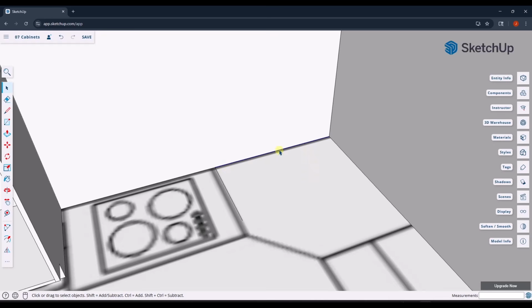So usually what I'll do is I'll select the edge, tap Q, I'll tap the up arrow key. That activates the rotate tool and locks it to the blue axis. And then I'll set a base point here. Click here to set my target point, and I'm going to tap Control in order to go into copy mode. So notice if you don't go into copy mode, it's just going to deform your edge. But if you do tap Control, it's just going to create a copy right here. But then we'll just do the same thing.